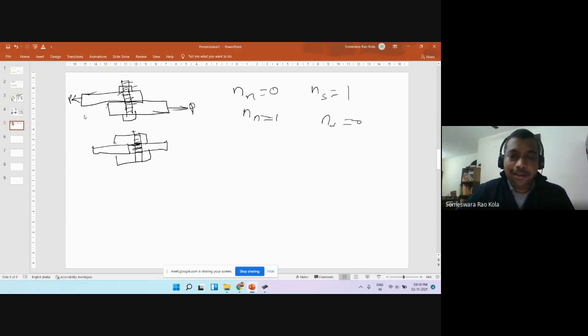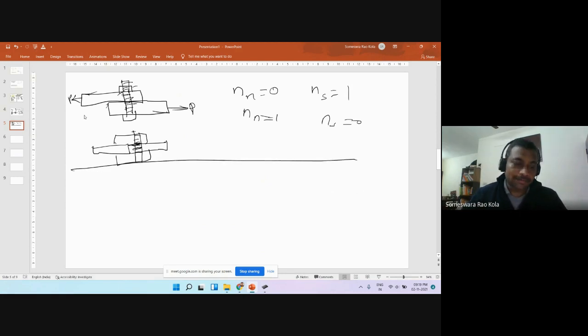Now, this is the shear strength, the design shear strength of the bolt. It is nothing but design shear stress times the area it is acting on, multiplied by the number of shear planes. Apart from that, there are some corrections to be made, so we don't just take it at face value.